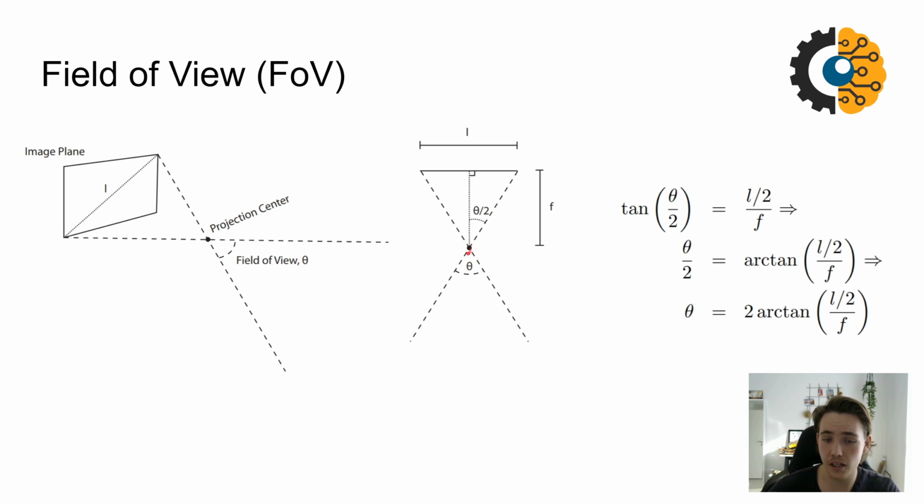So this dot here could be our camera, and then we have the field of view with these two dotted lines here, and this will be our field of view, and then this will be the optical center axis, which is the middle of our field of view. Then this angle here would be the field of view, how much we can see through our camera lens, and the half here would be the field of view divided by 2. And then we can find, if we know the length up here, the length of how much we can see with our camera, and the length